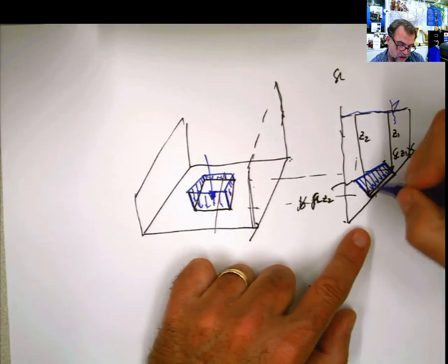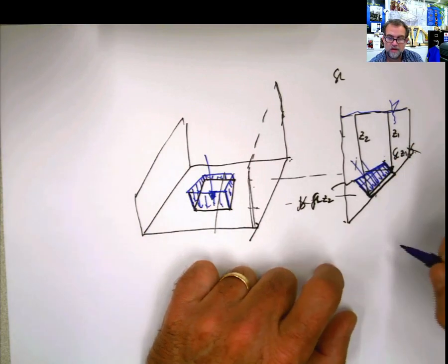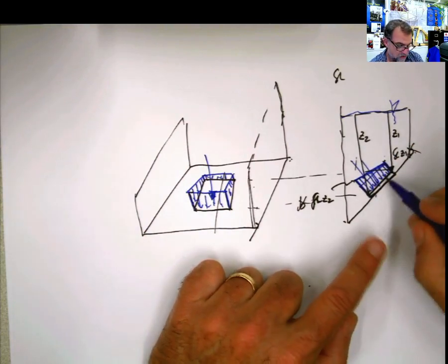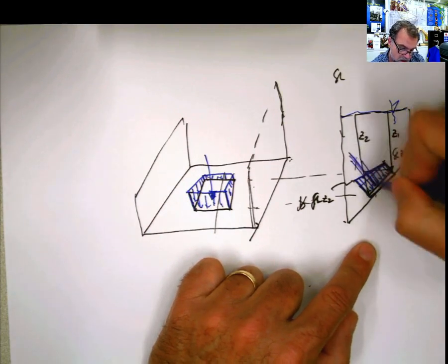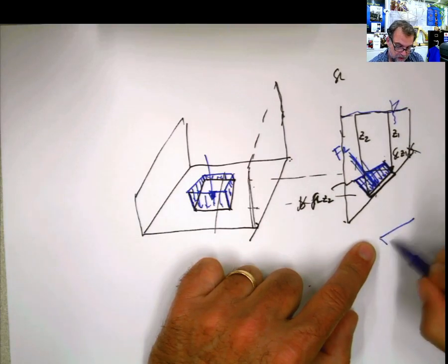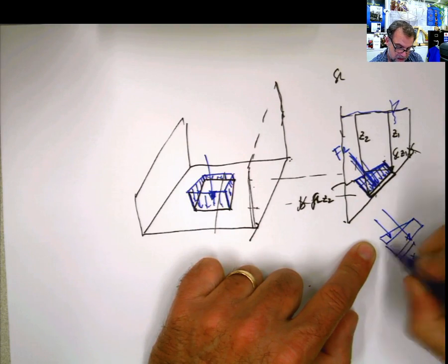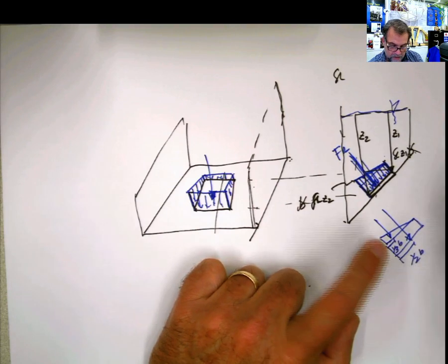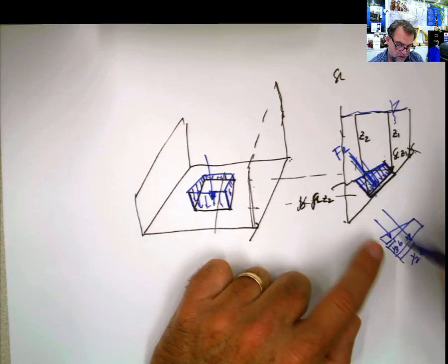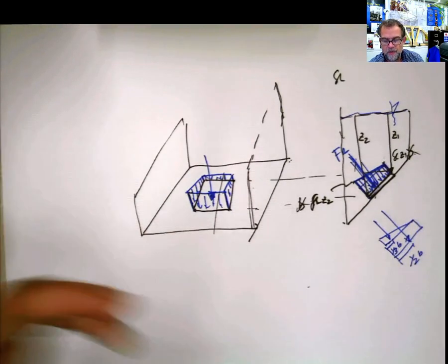Now the resultant of this, well, same thing. This is going to be a rectangular load and a triangular load. You calculate the resultant of the trapezium. What is going to be the total force? The resultant force is going to be the combination. You calculate the centroid of that one. Resultant force, you can combine this. If you don't know where the centroid is, you can combine this and this. Remember, this is 1/2 of the base, and this is 1/3 from this side here, not the base, whatever you call this distance. We call base the other one, but whatever you call this distance, you combine both of them, and the resultant force is going to be the area. Perfect, there's no problem with that.